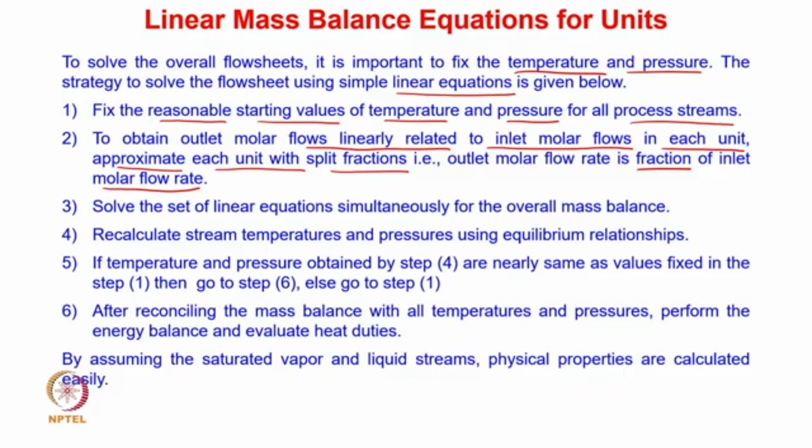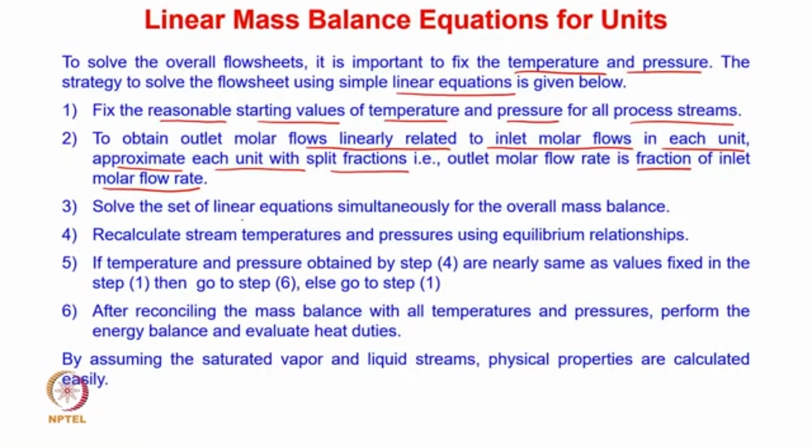Okay, so in this manner we can represent the output linearly with respect to the input. The third step is, all this set of linear equations which we have obtained for all the units, we solve these linear equations simultaneously for the overall mass balance. Once this overall mass balance is done, then we recalculate.